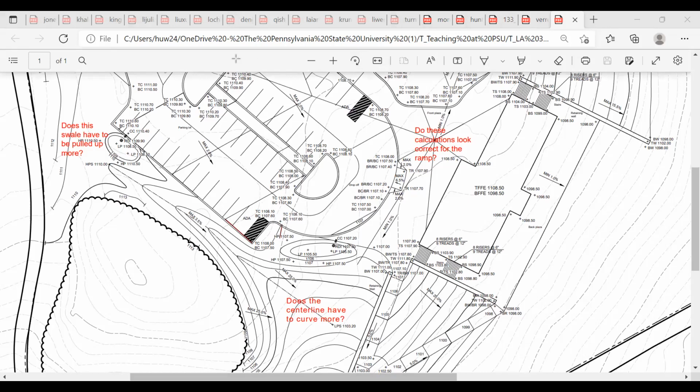So that contour needs to be, let's label it first. So if this is 9, and that is 8, and this is 7. Yeah, remember to label it on the high side. So this 07 is labeled on the low side, label it on the high side. Our 8 needs to be here,